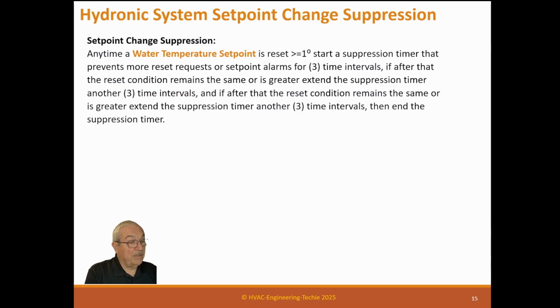And it may not be that it's not working. It may be because the mass is so large, it's going to take longer. That's what we're trying to do, is we're trying to get somewhere around 30 minutes of suppression of the alarm and suppression of the resets. So now, this is per set point. So if you have a whole bunch of set points, the others may be doing other things, but for each one, you're going to put this suppression formula in place, and it will help it stay stable.